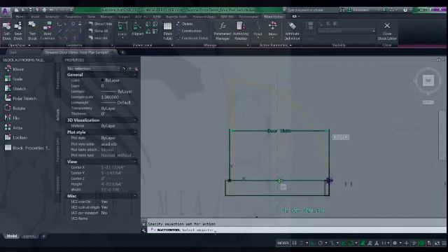And then it's going to ask me to select objects. And then I'm just going to go ahead and make sure that I select my flip parameter. So I want my flip parameter to be associated to my midpoint and my original parameter. Again, I'm sorry if that was confusing. I selected the move action, selected my parameter, selected my endpoint, and now I'm selecting my flip parameter. I'm going to hit enter.